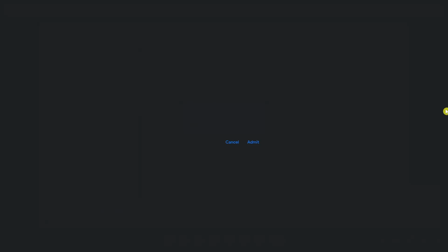Since we already have the name over here and we have the elements rooms, we need a way to set the parameter. So there is a command called set parameter in Revit, which we can obtain again by going to Revit, going to elements, elements under elements, and then going to set parameter by name. It clearly gives you a description that it sets one of the elements parameters, the element in this case being the room, by the given value. Okay, so let me get the node over here. So you can see over here we have the node, which is called element.set parameter by name.